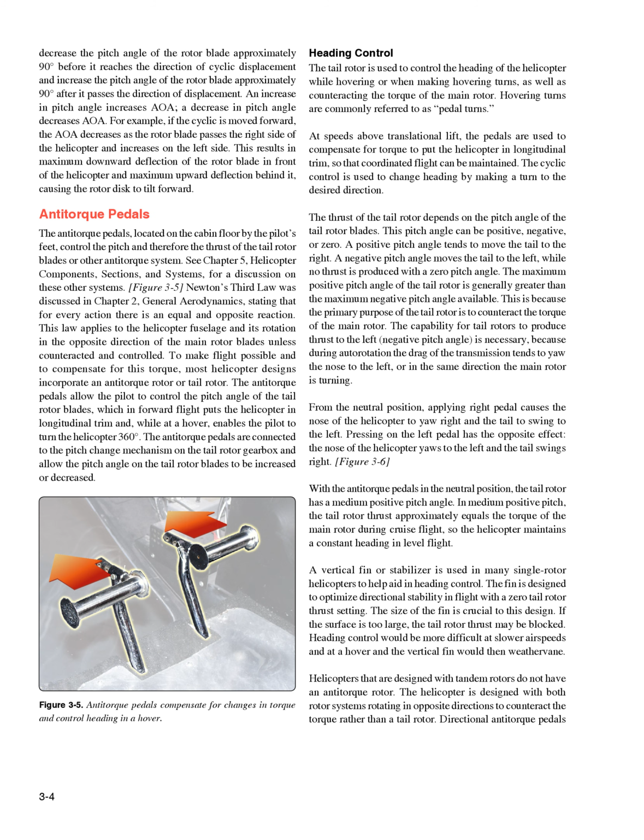The anti-torque pedals allow the pilot to control the pitch angle of the tail rotor blades, which in forward flight puts the helicopter in longitudinal trim and, while at a hover, enables the pilot to turn the helicopter 360 degrees. The anti-torque pedals are connected to the pitch change mechanism on the tail rotor gearbox and allow the pitch angle on the tail rotor blades to be increased or decreased.